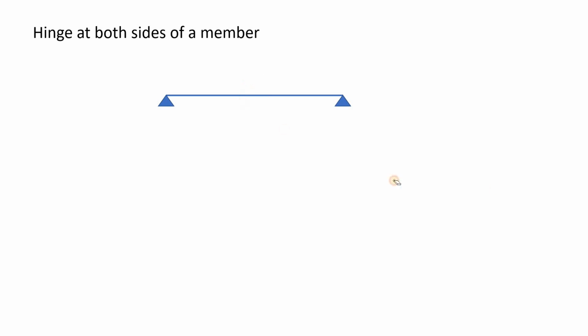Okay, now that we have covered all of this, another thing I should mention to you is that if there's a situation like this, let's say this is a joint, one member goes from here, another member goes from here, and the angle between them is 180 degrees, and let's call these members AC and BC. In case the AC member turns out to be a zero force member, we don't know yet, but once we are doing our calculations we see that AC is a zero force member, then subsequently we can easily tell that the BC member is also a zero force member.